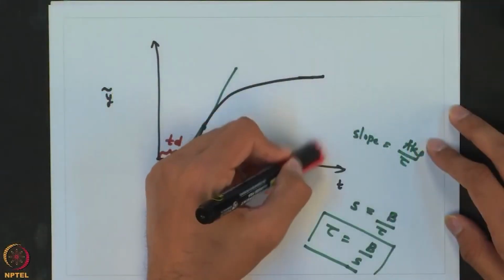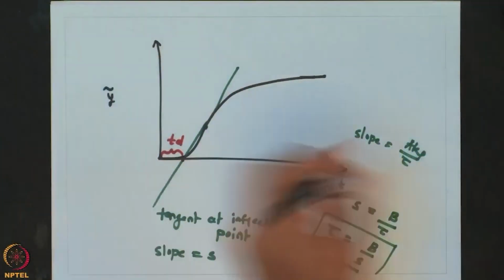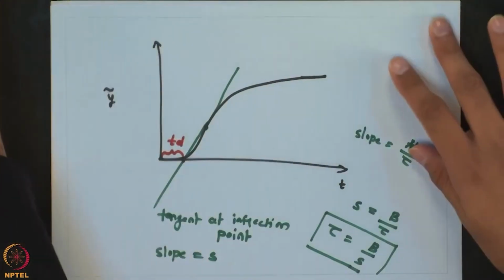Now I would also like to make a small note that sometimes the order of the system is very high, and in that case running a step response and trying to get the final output takes a very long time. A typical example would be if we are interested in finding the transfer function model between the product purities of the distillation column and the feed composition.